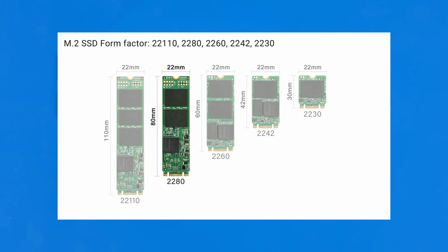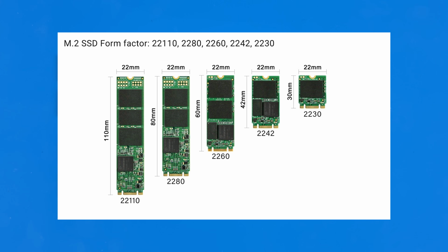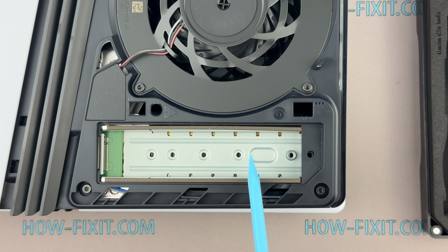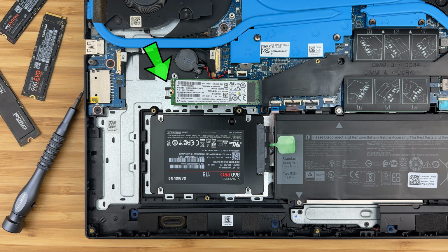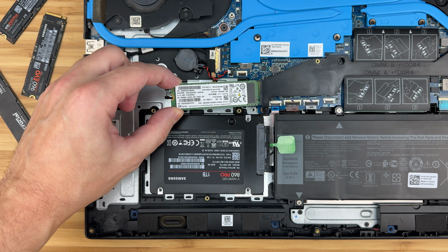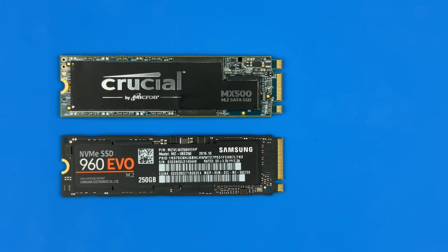Before purchasing an M.2 SSD, it is essential to determine which M.2 size your device supports. For example, the PlayStation 5 supports all 5 subtypes. Computer motherboards generally support up to 3 subtypes. Laptops typically support only one M.2 SSD size, though some models may support 2.